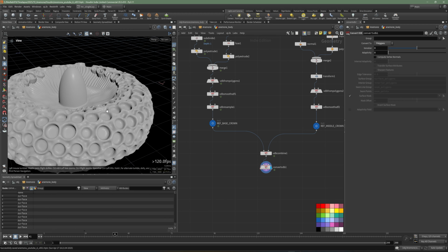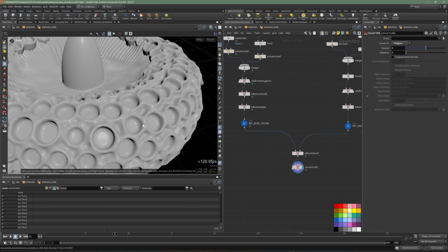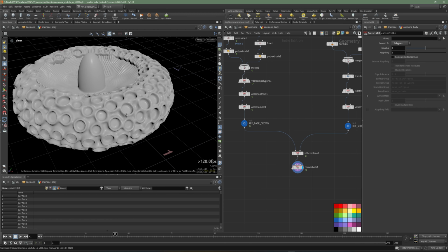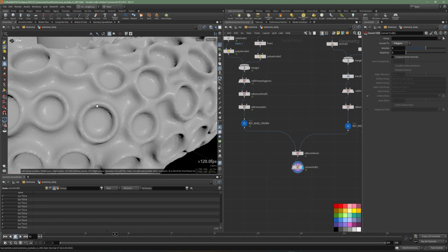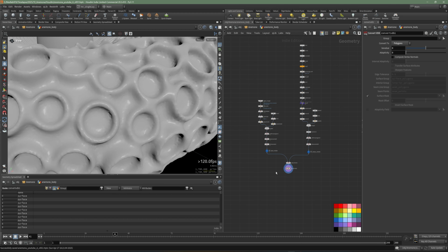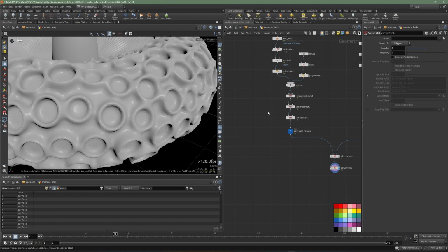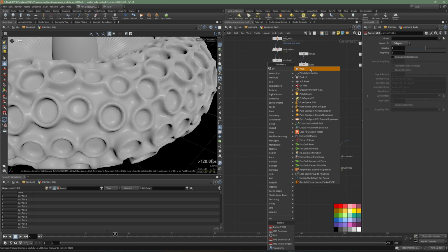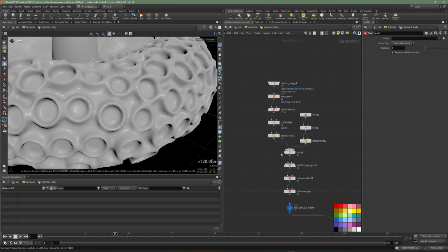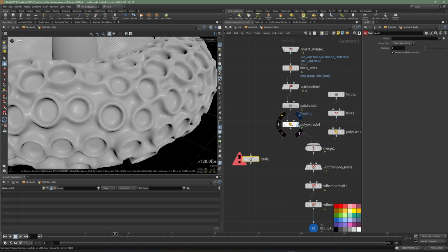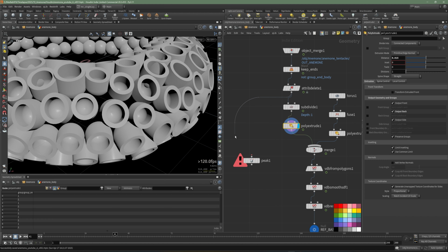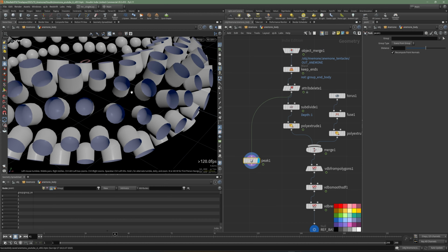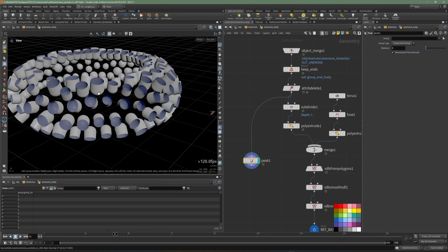Another step we're going to do here, before going to rendering, we need to create a mask from these areas here. These contact areas should create a mask for using the shader in the Redshift. Let's create this right now. For this, super simple. Create a peak node, connect from this node here, polyextrude. Connect here from this attribute node here. We just need the original, trimming the tentacles.